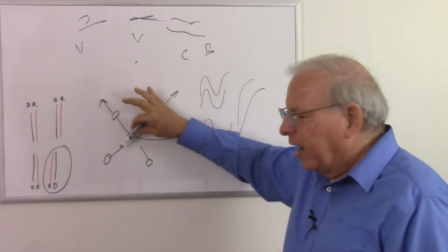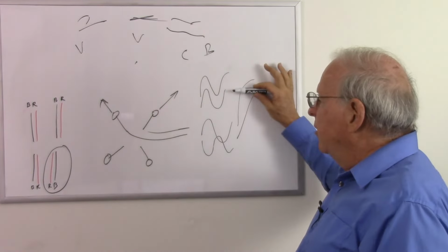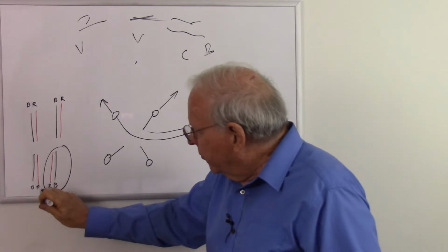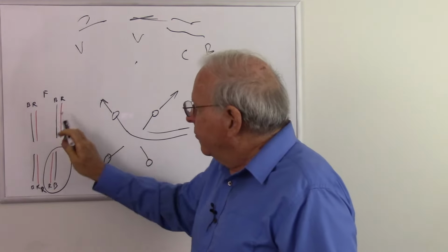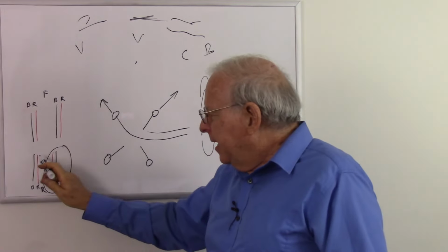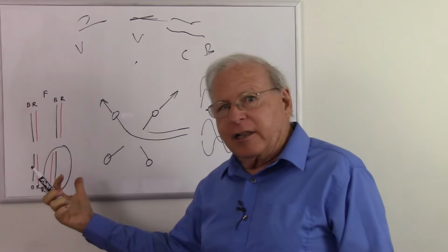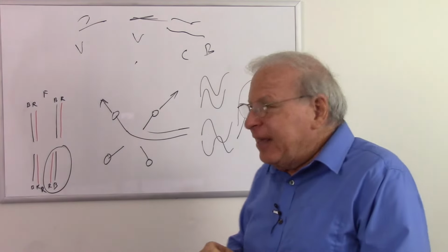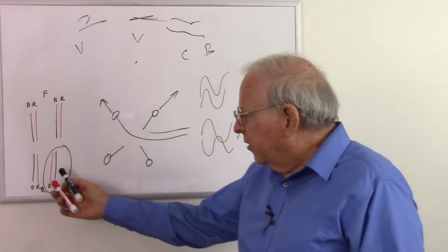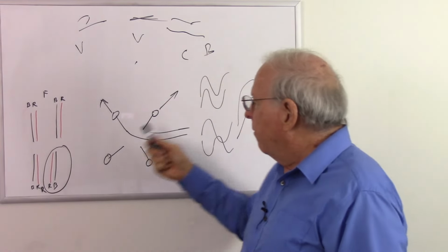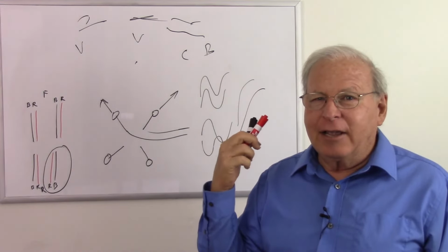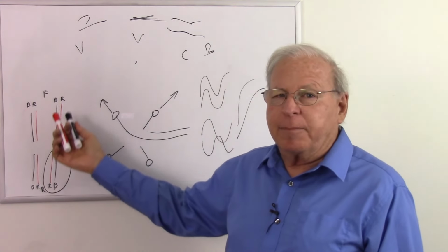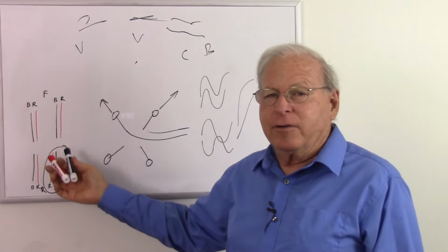So basically, we're flipping the wires on one microphone, mixing it into 2 channels. Then when we come back out, we flip the wires on one speaker. And notice this is the rear, this is the front. So the front speakers get the sound normally. The rear speakers, we either electronically or physically flip the wires, and that directs those sounds to the back. Theoretically, it doesn't work because there's only a 3 dB difference between the front and the back when we use this method. But the audio system in our brains is awfully good, and it can separate that out much better than is theoretically possible. And trust me, it sounds great if you do this.